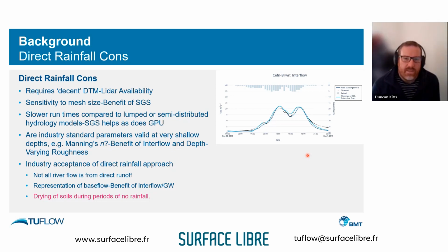And we don't know yet which is the best result in our HEC RAS model. Okay, so possibly one to cover in another webinar, but certainly with subgrid sampling, the one thing you do need to be aware of is to make sure that any hydraulic controls are suitably enforced. So the use of break lines, for instance, you probably need to be a bit more proactive with than using a single elevation point per cell.